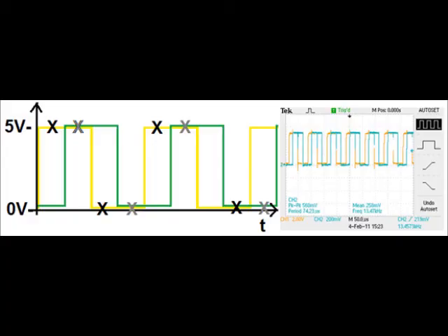The idea of measuring the speed is quite easy, just counting the signals for a certain period of time. The difficulty is that a frequency above 12 kHz can't be analyzed by counting anymore, because the microcontroller is too slow. I have to deal with frequencies up to 40 kHz.